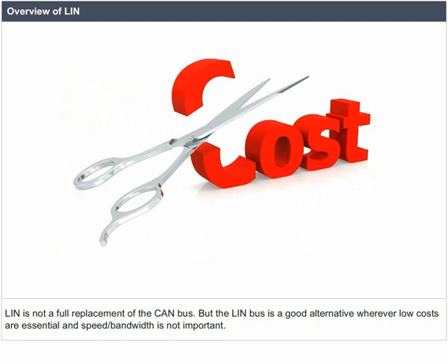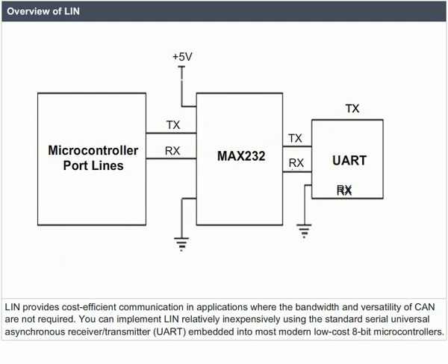LIN is not a full replacement of the CAN bus, but the LIN bus is a good alternative whenever low costs are essential and speed or bandwidth is not important. LIN provides cost-efficient communication in applications where the bandwidth and versatility of CAN are not required.